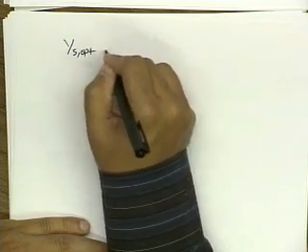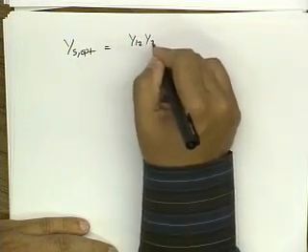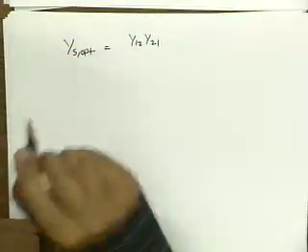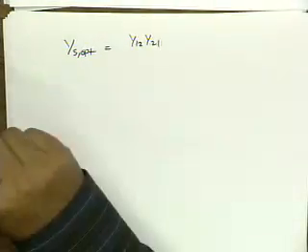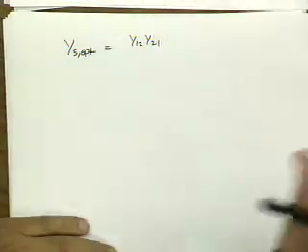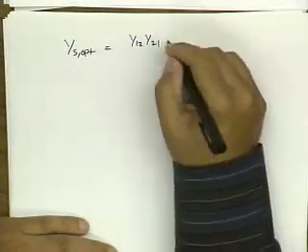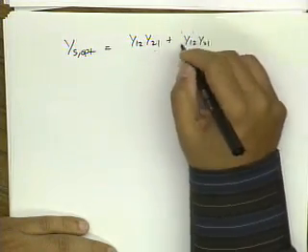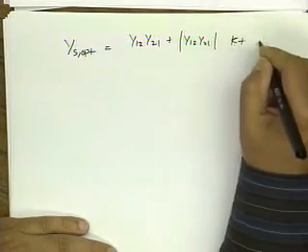For instance, you may ask how I got the optimum source when I only calculated the optimum load. Well, you calculate the optimum source by simply saying that Ys should equal Yin star. You go through the algebra and derive these equations.